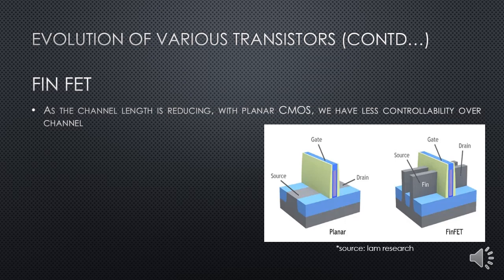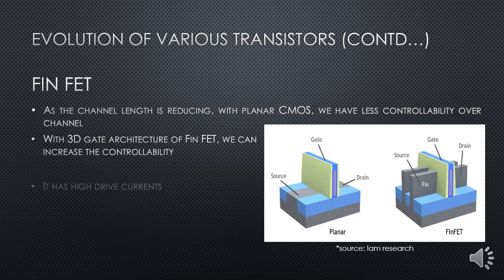With this, we increase the controllability that we have in the 3D gate architecture of FinFET. We can increase the controllability of the formation of the gate. It has high drive currents, by the way. FinFET will have high drive currents compared to planar CMOS. It has faster switching times also.